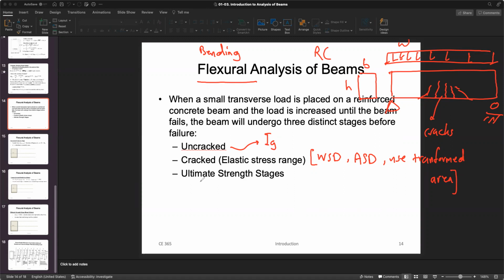All right. And then you're going to pass, still going through, because you know that the concrete wouldn't fail. What was the stress strain diagram for the concrete? If you remember, you go up, you come down like this, right? So here is F prime C. This is like a linear region, I would say. And then you're cracked in this region, and then you pass through the elastic region, you go to the ultimate strain, and you come down and fail around.